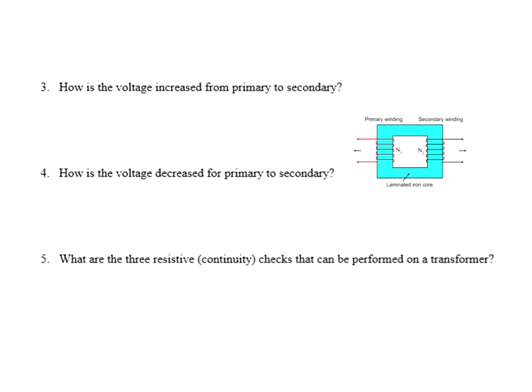Well, we have an inductor in the primary, and if I check between here and here with my ohm meter, it should read very, very low because it's just turns of wire in there. But if I read from here, primary to secondary, I should get infinity ohms because there's no direct electrical connection between here and there. You're passing electromagnetic flux or lines of magnetic force between them, but there's no direct electrical connection.